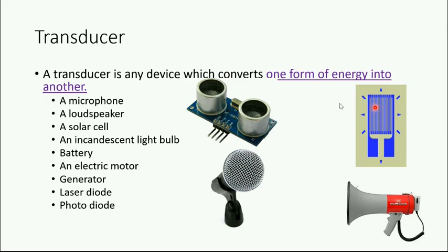And this is a strain gauge. Without any force or tension, there is a definite fixed resistance, suppose it is 10K. When a force or tension is applied, deformation happens in this structure, and so the resistance changes. This can be connected to a bridge circuit, and so a force is converted into an electrical signal.